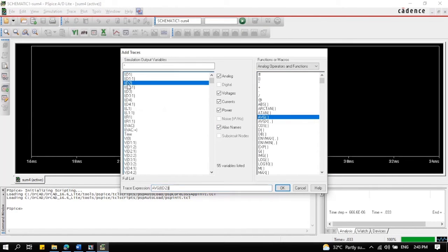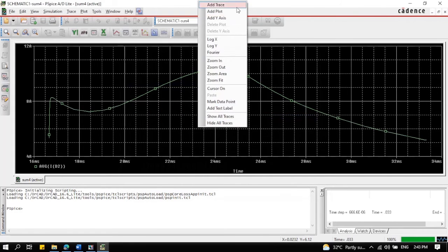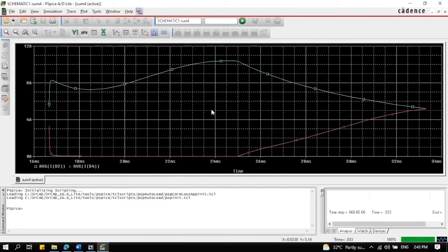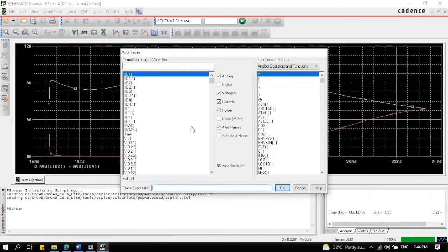So from the mathematical solution earlier, we observed that we got the values for the harmonic number 2 and 4. So here, we're going to use that. We're going to get the average load current and RMS load current for D2 and D4. That stands for the N2 and N4. So here, the average load current, we can observe that for D2 and D4, N2 and N4, they have almost the same average load current. And now let's check for the RMS.